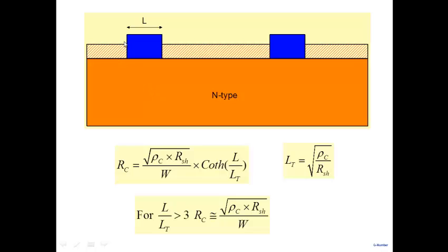Well, you can do that. This shaded region that you see here is silicon dioxide. So before you deposit the contact, you can add dopant selectively in this region here and in this region here. What it is saying is that often you will find that the doping under the contact is usually kept very, very high.